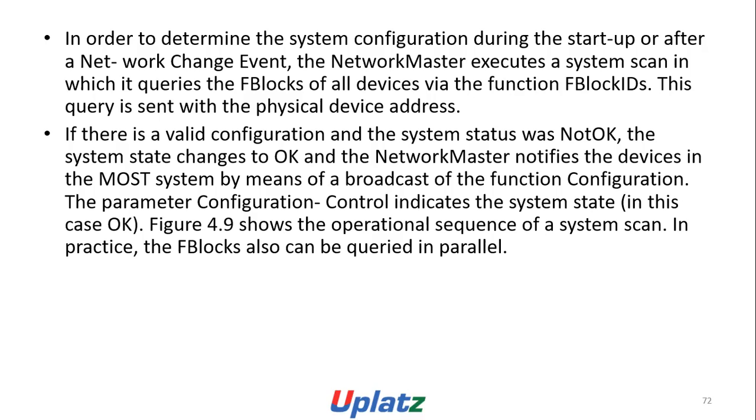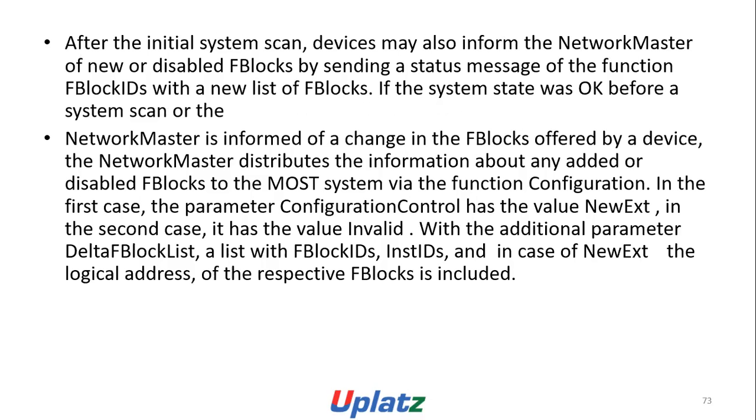In practice, FBlocks can also be queried in parallel. After the initial system scan, devices may also inform the network master of new or disabled FBlocks by sending a status message of the function FBlock IDs with a new list of FBlocks in the system state.